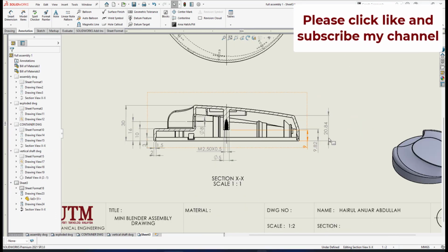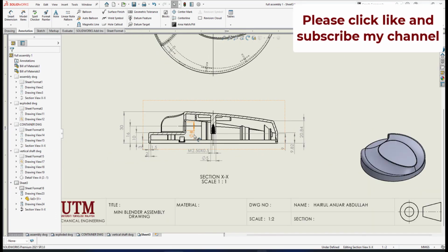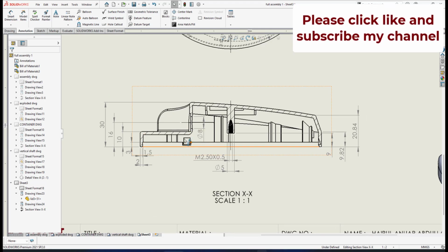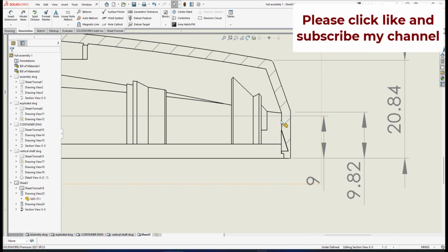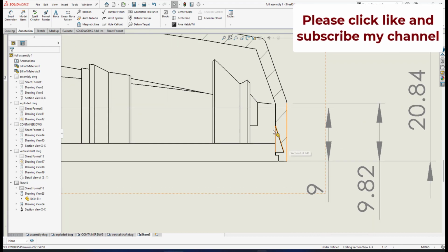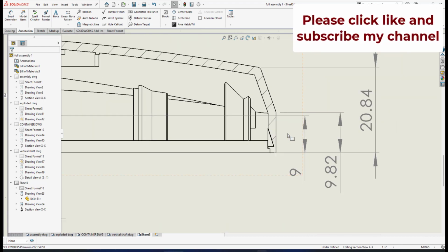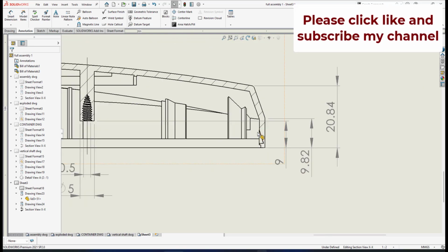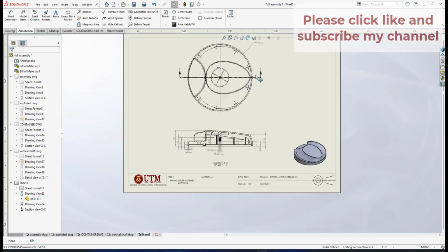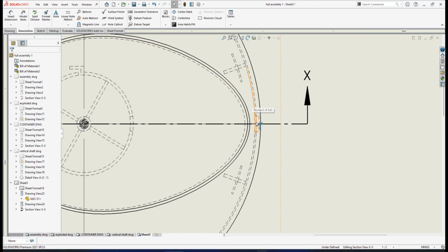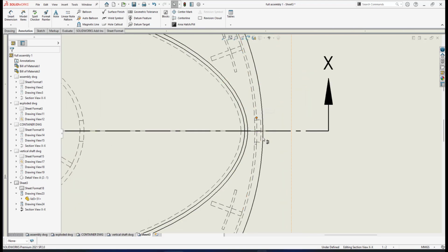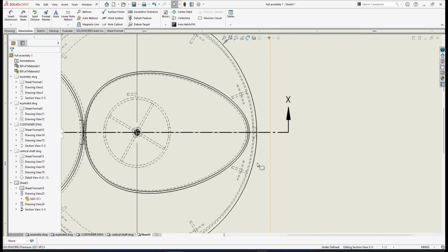As you can see, we have a snap feature here. For this lid, we have a snap groove. So this is the cutting view of this snap groove. This profile is like a triangle. I need to dimension the size of this groove, since as we can see, this cutting plane is really cutting this snap groove at the normal section of it.